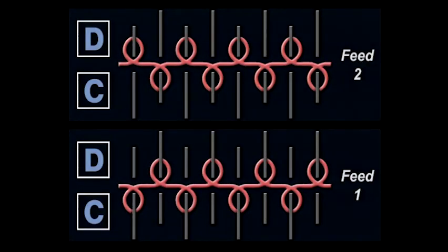At the first yarn feeding position, the odd-numbered cylinder needles knit, and the even-numbered dial needles must knit. On the next yarn feeding position, the needles that didn't knit at the first feed will now knit. It's easy to see that it takes 2 feeds to knit 1 repeat of interlock. Because the loops interlock and alternate from the front to the back, the structure of interlock fabric is much more rigid and dimensionally stable than that of a rib fabric.